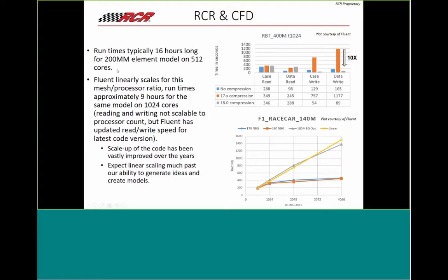So Fluent is linear scale in the mesh size for the number of processors that we're operating. So we're operating down in this region here because we're trying to turn around cases as fast as we possibly can. But we're also interested in operating in the most efficient region possible. And because of that, we can scale up or scale down without worrying too much about compute efficiency.